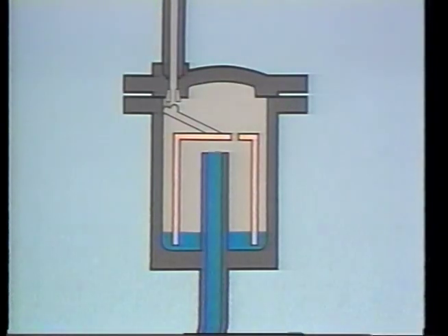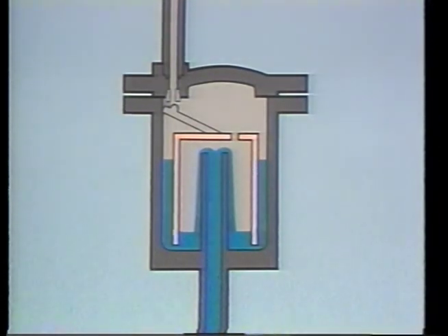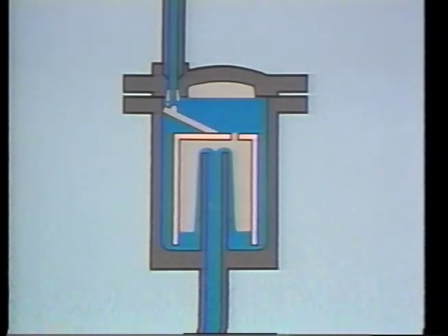Cool condensate enters the inlet pipe. It flows into and then out of the bucket, traveling up between the outside of the bucket and the inside of the casing wall. Finally, it flows out the trap valve.